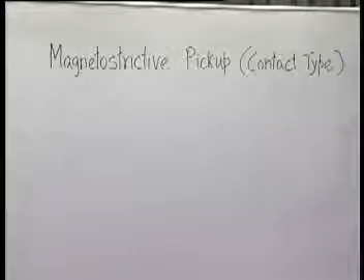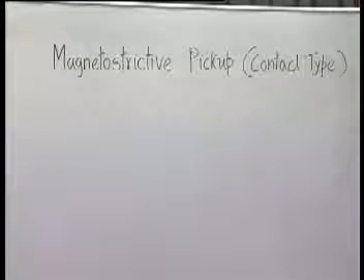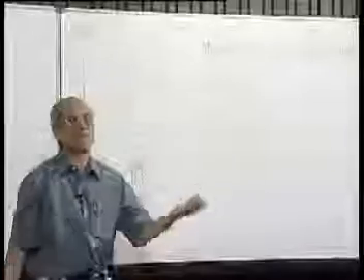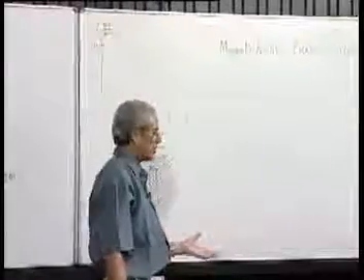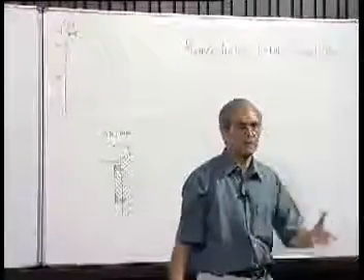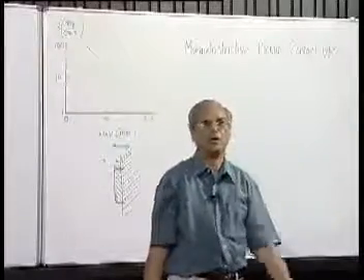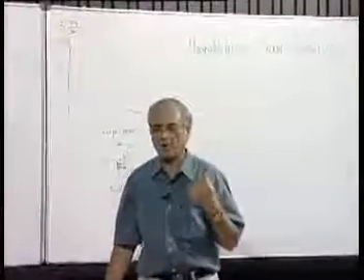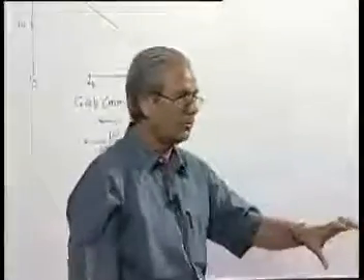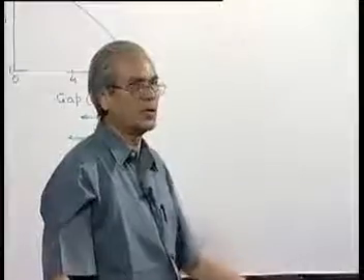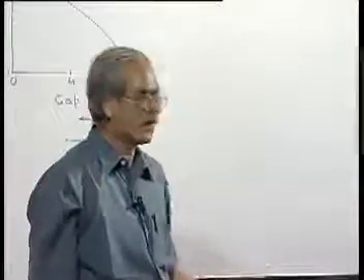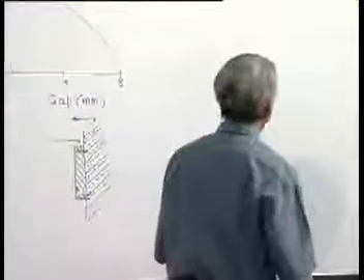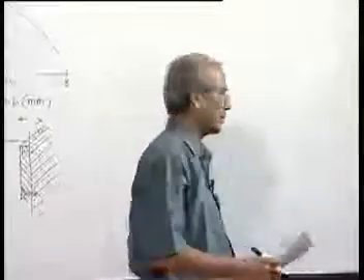What is magnetostriction? I hope it's all known to you, but I will give a very quick reference. When you enter a substation or such installations where there are no moving parts, but only transformers, which are again stationary objects, we still get some humming sound. Or when a motor gets jammed so there is no rotation, but when alternating current flows, we get a humming sound. Now what is this? This is nothing but the result of magnetostriction.